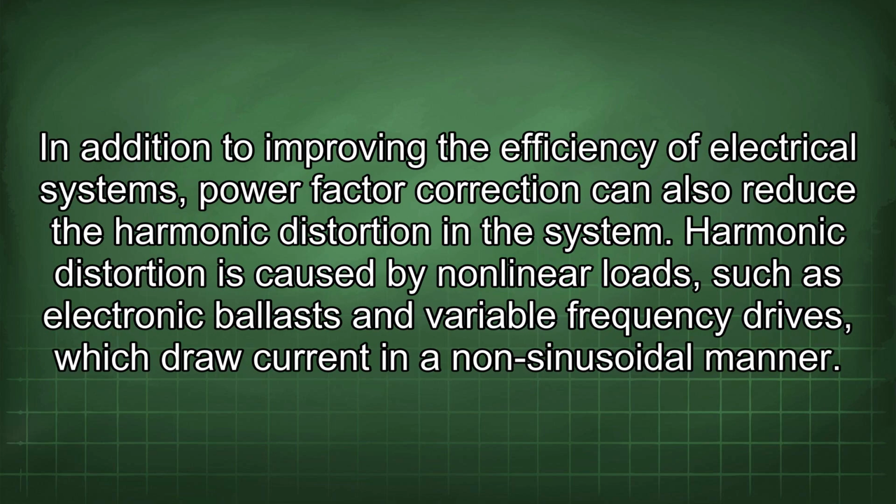In addition to improving the efficiency of electrical systems, power factor correction can also reduce the harmonic distortion in the system. Harmonic distortion is caused by nonlinear loads such as electronic ballasts and variable frequency drives, which draw current in a non-sinusoidal manner.